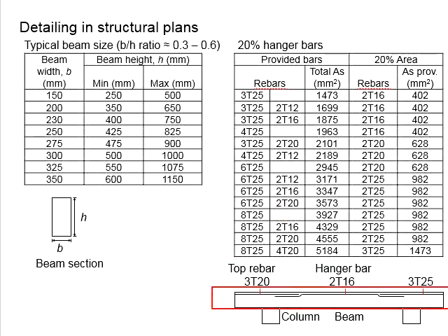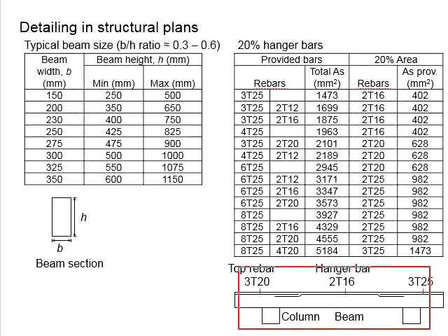Let's say now you have a continuous beam here, where there are extensions from here and extensions from the other side. This is just one stretch of the continuous member, and you know that at the support you will need to provide tension reinforcement bar at the top of the beam because of the negative moment. This also happens at another support of the continuous member, where you will need to design an adequate length for the top main reinforcement bar to stop within the members, so that it is able to take this negative moment. The same goes for the other support here.